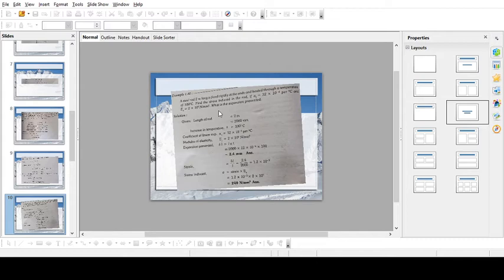Now, when a composite bar of two materials is heated, they experience different expansion if free to do so. Since these ends are rigidly fastened together, they expand to an equal length, as given in figure C. Now, compressive stress in bar 2 reduces its free length by x2, and the tensile stress in bar 1 causes an expansion of x1.